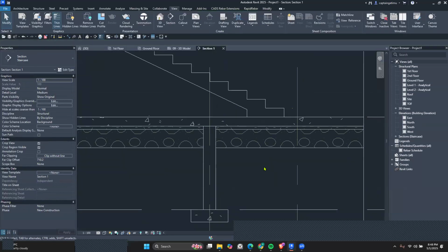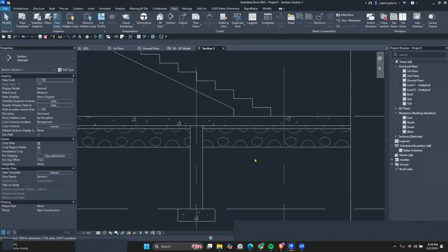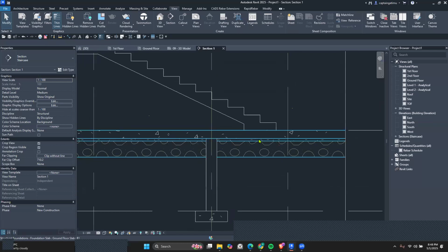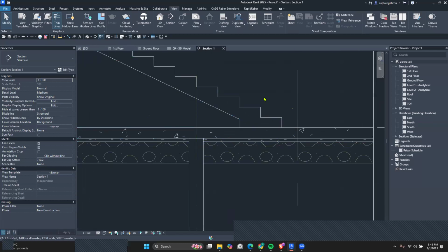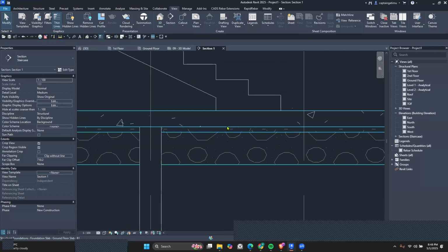After you go to your slab now, you can see it looks visually better, and you can easily tell the different layers that you're going to be using. So I'm going to take you back to the cut panel, and this time I want us to create a cut profile between two layers. To do that, we will go to the view. Remember, to access the cut profile, you go to the view tab and then click on cut profile.